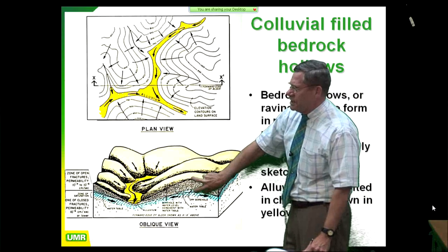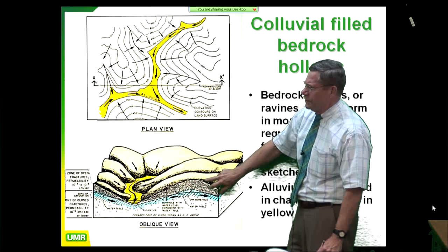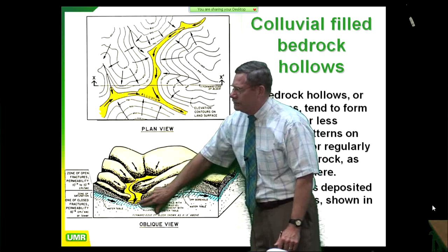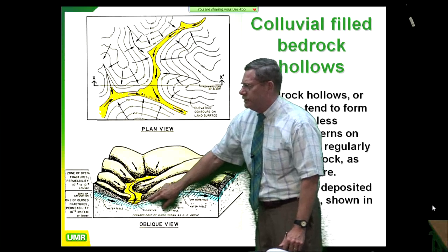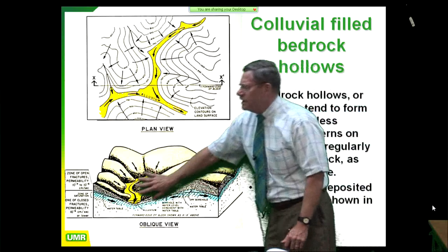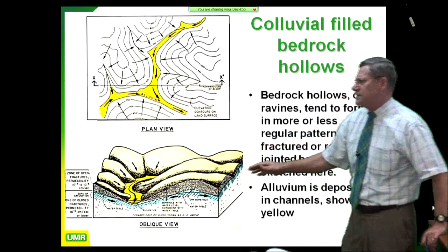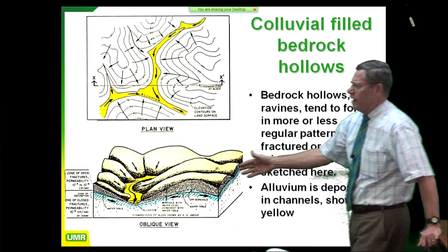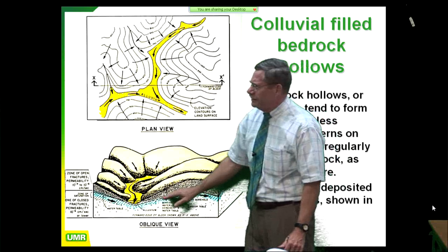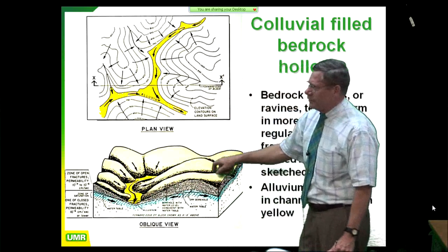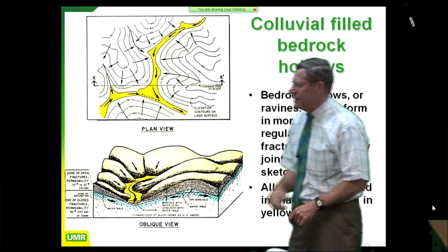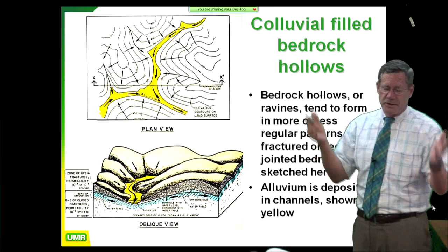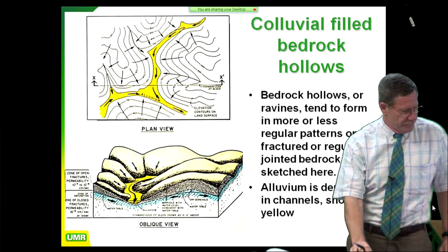Now, if you actually look here, the water table is deepest, typically, underneath a bedrock ridge, under a knob. And as we approach the channel down here, the groundwater gets closer and closer to the ground surface. And we really see this obeyed all over the loess-covered, dissected uplands of Missouri, especially around the St. Louis area. You want to look at a groundwater map that my postdoc, Jaewon Chung, has done. We've been comparing it with all the borings everybody does all over St. Louis, and we're always within a meter, just using a theoretical model which has a good topographic coverage, digital elevation model.